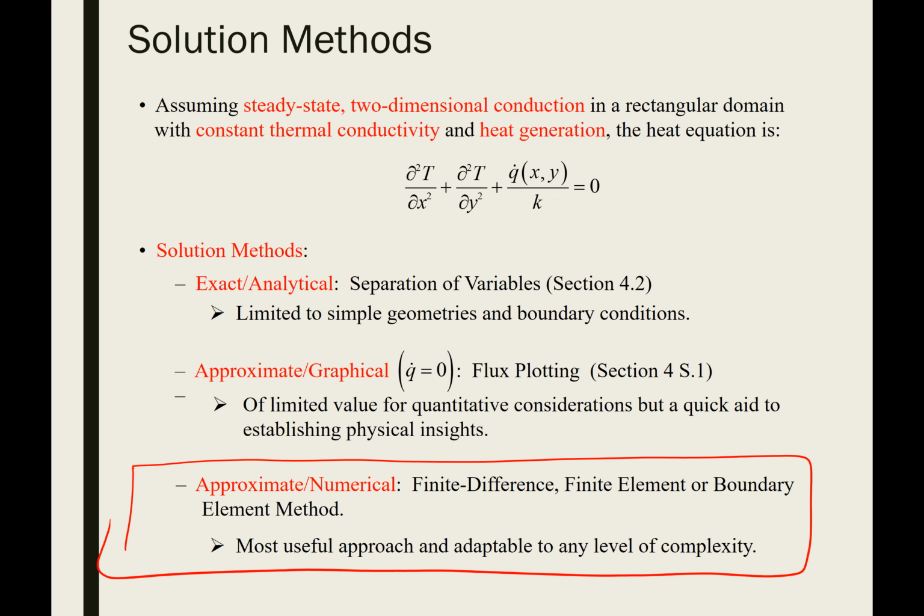If you remember when we derived the heat equation, we took our imaginary solid and broke it up into tiny little cubes, and we applied an energy balance to one of those cubes, and then eventually we shrunk that cube down to be purely differential. So it has no real dimensions. We took the limit as delta x, delta y, and delta z all go to 0. So that means our energy balance basically becomes these infinitesimally small little blocks.